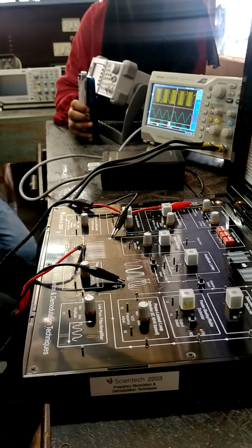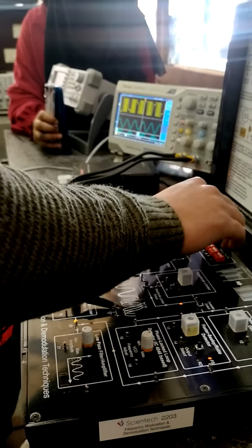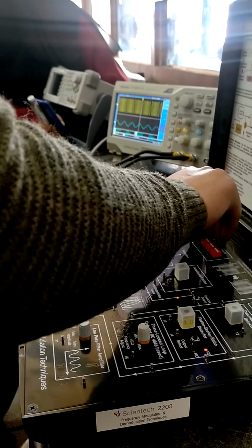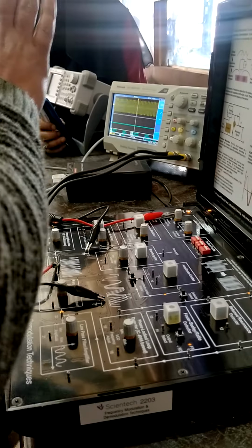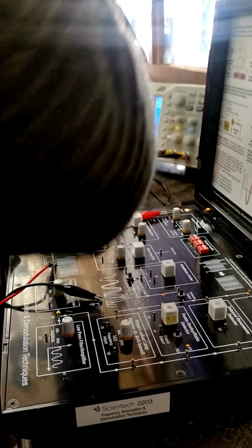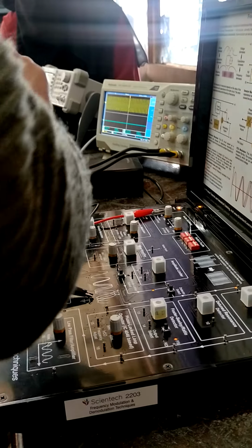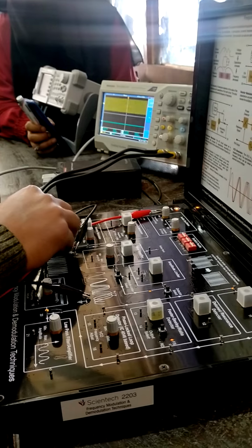So in the frequency modulator, how will you calculate the beta value? First of all, you can find out the carrier frequency at this particular point given to the frequency modulator by cancelling out the amplitude of the signal, that is, not providing any signal. At this time I'm not providing any signal to the frequency modulator, so this is the unmodulated carrier. You will notice its frequency and amplitude. You can also change its frequency by this.